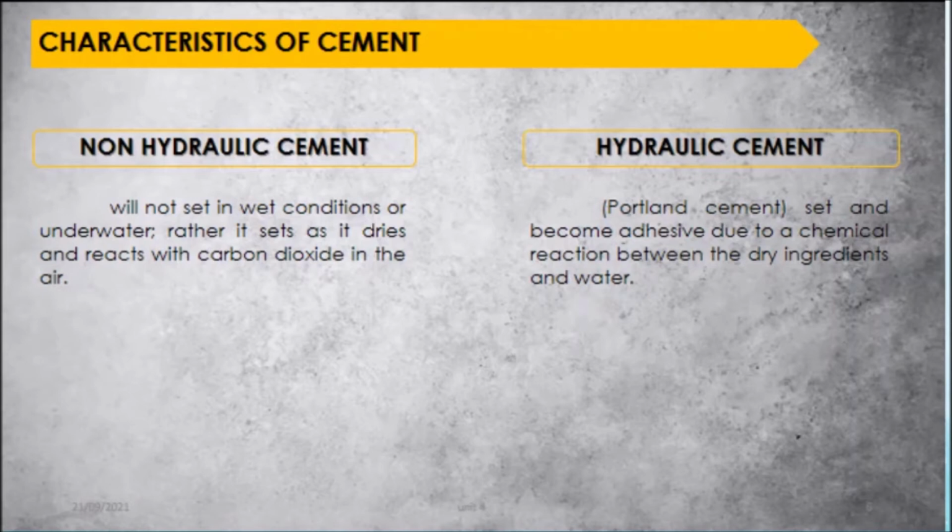Non-hydraulic cements are created using materials such as non-hydraulic lime and gypsum plasters, and oxychloride. After non-hydraulic cement is utilized in construction, it must be kept dry in order to gain strength and hold the structure. When non-hydraulic cement is used in mortar, the mortar can set only by drying out and therefore gains strength very slowly. Due to the difficulties associated with waiting a long period for setting and drying, non-hydraulic cement is seldom utilized in this modern time.